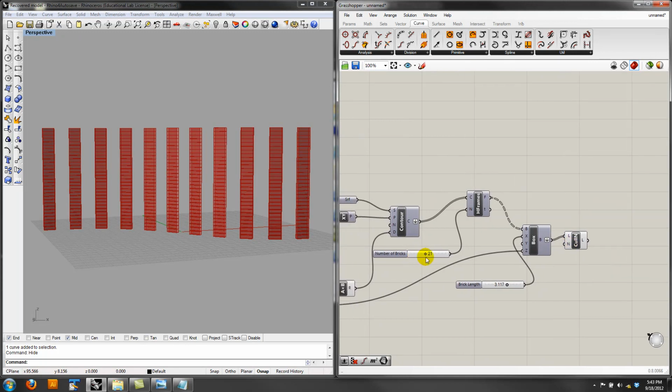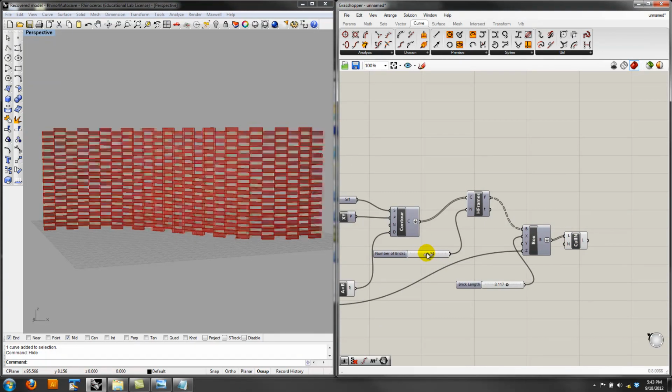And you say, oh, Nick, it didn't work. But if you look at this, it actually only works with even numbers. Because if you have an odd number, the rows align with each other, and essentially you're not getting any effect. So to make a successful checkerboard pattern, you have to have an even number of objects in each row, make sure that you flatten things, and then you can apply the cull n pattern with a value of 2.